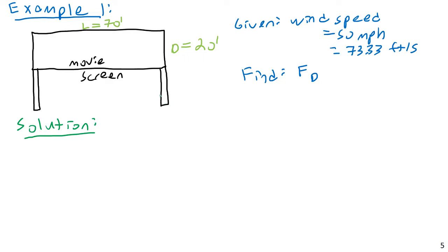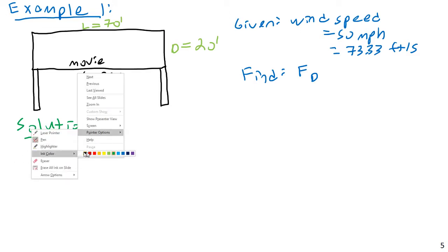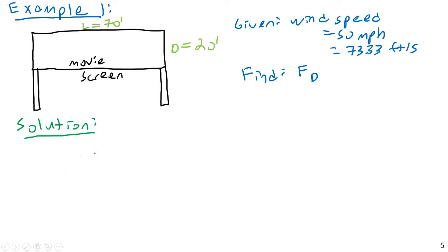Its absolute velocity V is actually 0. So we could throw this problem directly into our power formula, and because the sign isn't moving, it wouldn't require any power to overcome the drag force. That, of course, makes intuitive sense. A stationary billboard does not need an engine attached to it in order to overcome the force of drag from wind applied to it. It just has to have enough internal support to resist those forces.